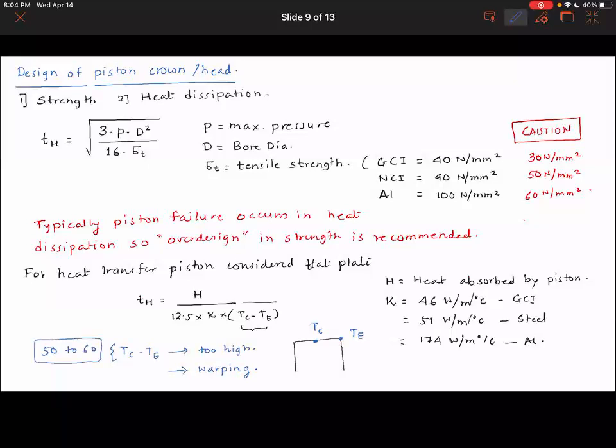Because if it's higher than that, then the material expansion would be uneven, and that would lead to localized stressing and then warping.